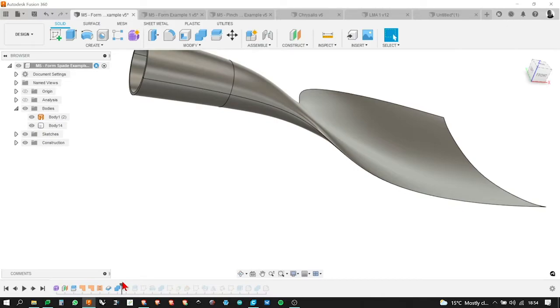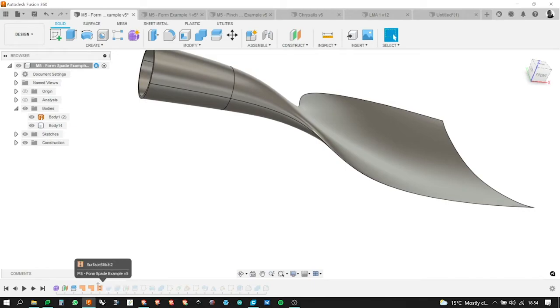So the red line showing there's a problem. A green line is basically those two surfaces will stitch together. If there's a red line, it's basically open. There's nothing to stitch to. So perhaps your two elements aren't stitching correctly. So let's go back and have a look at this one, for instance.